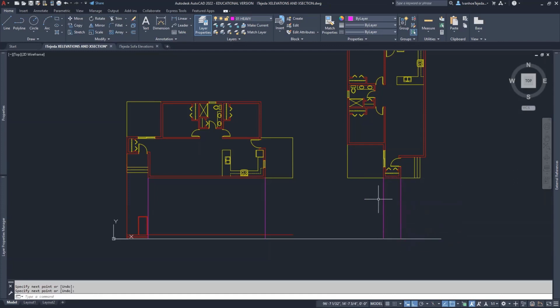And then for the other lines, because they are further back, now I want those to be medium. So I select or click on medium, make that my current layer, and then L again for line, enter. And I take this line straight down and it goes perpendicular, enter, and then enter again. And this line straight down like this and enter.